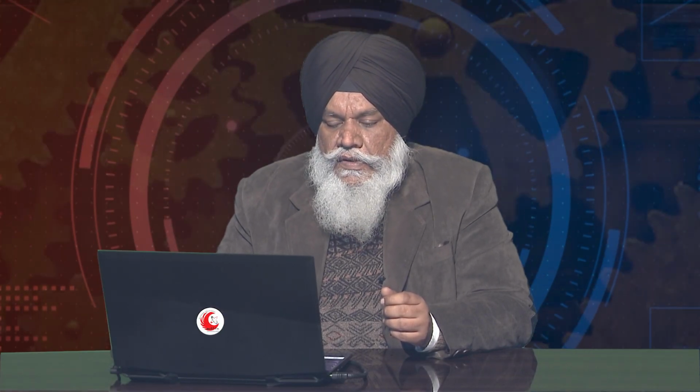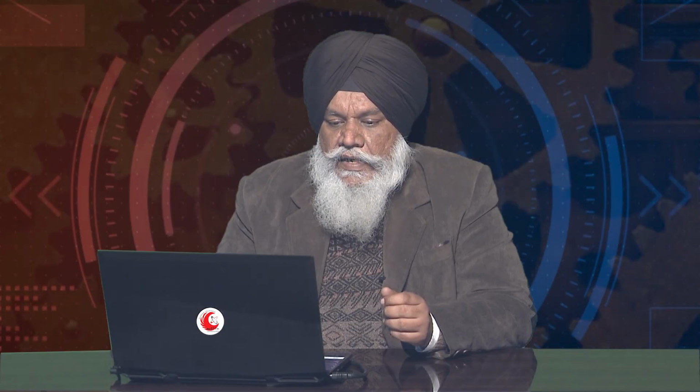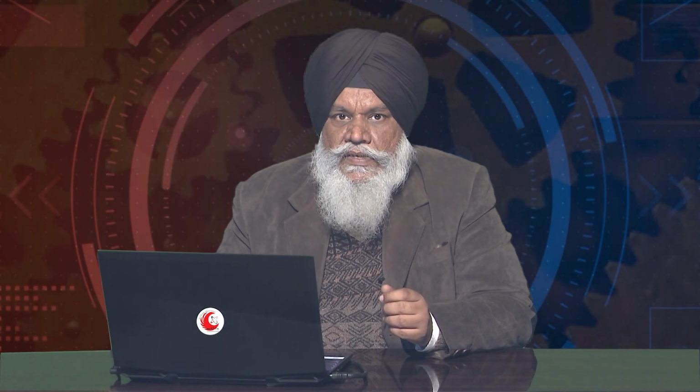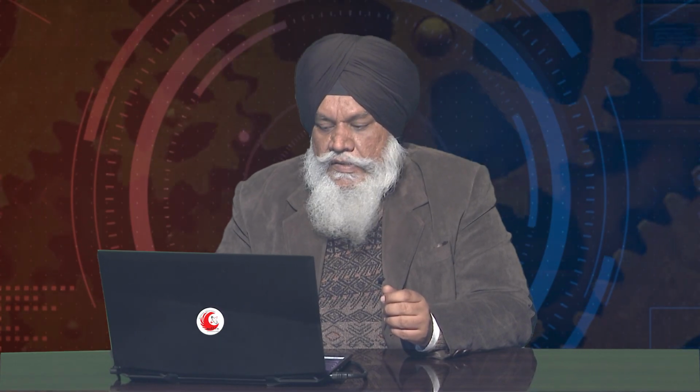I have used Cura, but any open source software can be used for this. As a standard operating procedure, what I need to know is the combination for the selection of layers for the dual thermoplastic material, then 3D printing of the flexural specimens as well as tensile specimens, because the geometry has already been fixed. Then we are interested in characterization on a tensile testing setup, basically the UTM. Then the fractured surface analysis, followed by understanding of the surface roughness that has been generated. In this case, we have used an open source image processing software, Gwyddion.